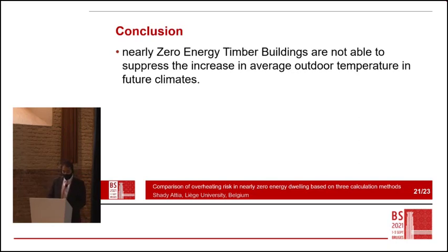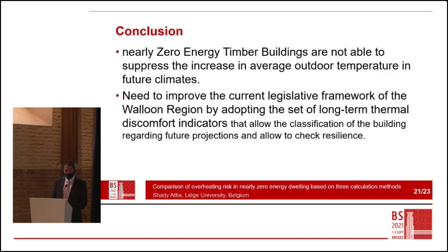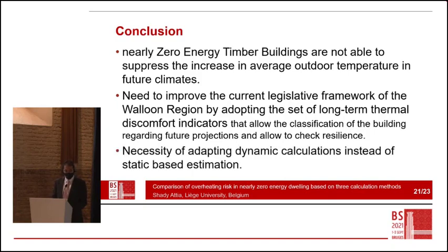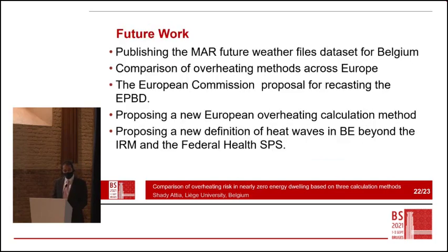Conclusion, nearly zero energy timber buildings are not able to suppress the increased average outdoor temperature in future climate. There is a need to improve our current legislation framework of the Walloon region in the south of Belgium. I cannot talk in the name of Flanders. By adopting a set of long-term thermal discomfort indicators that allows the classification of the building regarding future prediction and allows to check the resilience. And there is a necessity to adapt the dynamic calculation instead of the static, because when you look at our neighbor country, the Netherlands, they have a dynamic approach. The United Kingdom has a dynamic approach, and it would be interesting to look at that.